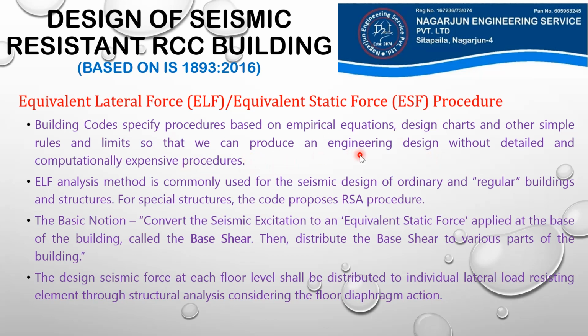That means when we really want to design a structure, or perhaps a complex structure, what we have to do is first determine the hazard level of the site in which our structure is going to be built, and based on that hazard level we have to determine the acceptable response of a structure, and then design and analysis has to be performed in a sequential manner.